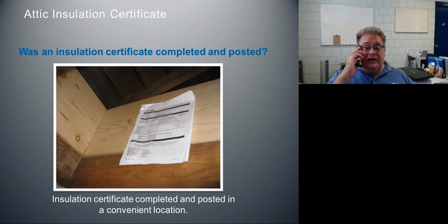Okay. Coming out of the attic, how about an insulation certificate? Do we have one that is completed and posted? And I would also recommend that you talk to your crews about getting into the habit of stapling up a bag that they have used to fill the attic.